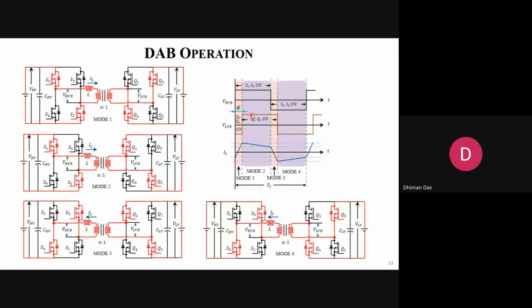So the primary side of the bridge is a full bridge. That means you can have a pulsating plus and minus. Now, at the secondary, the low voltage side also, you can have a plus and minus waveform. When you reflect this pulsating, or square, waveform to the secondary or high voltage side, it will just be multiplied by n times, because this is an n is to 1 transformer.